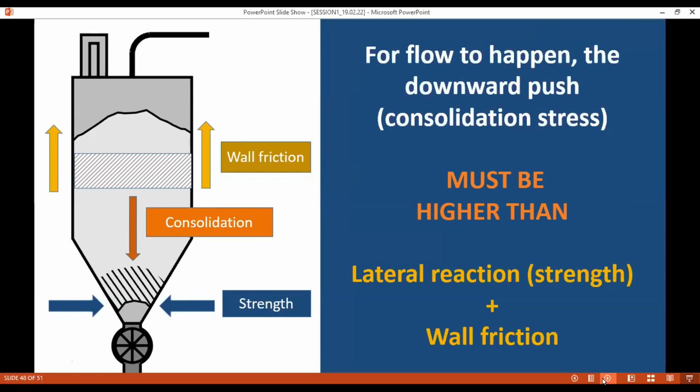But then also you have to be careful. This is only good, let me again tell you, if you have a cohesive ash which is not falling. Otherwise, if the ash is very free flowing, coarse, Group B material, and you give it extra fluidization air, too much ash is going to fall. And again, as I said, the synchronization is very important.